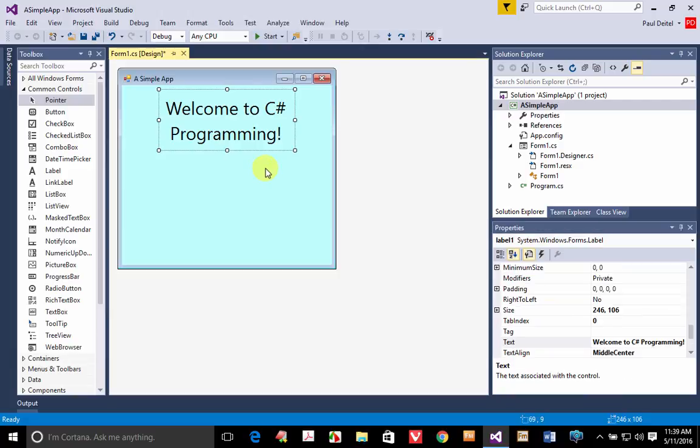So now let's go ahead and get the picture box onto the user interface by dragging it from the toolbox into the design area. Now you might have seen quickly a blue line appear. There it is. That's a snap guide to help you align the left edge of the picture box with the left edge of the label above it. If I drag further to the left, I'll see a snap guide indicating the recommended positioning distance of the picture box from the left edge of the form. If I drag down, I can see a recommended distance guide from the bottom edge of the form as well.